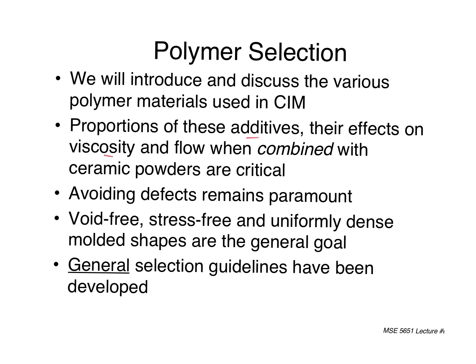The proportions of these additives and their effects on viscosity and flow when combined with these powders are critical. So this issue of flow: we need to get it to go into the die. The die has nooks and crannies, and it needs to fill those spaces efficiently.